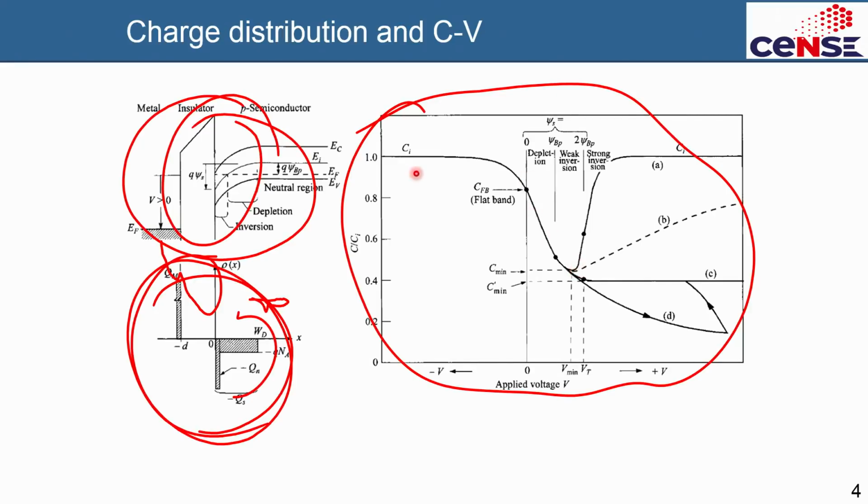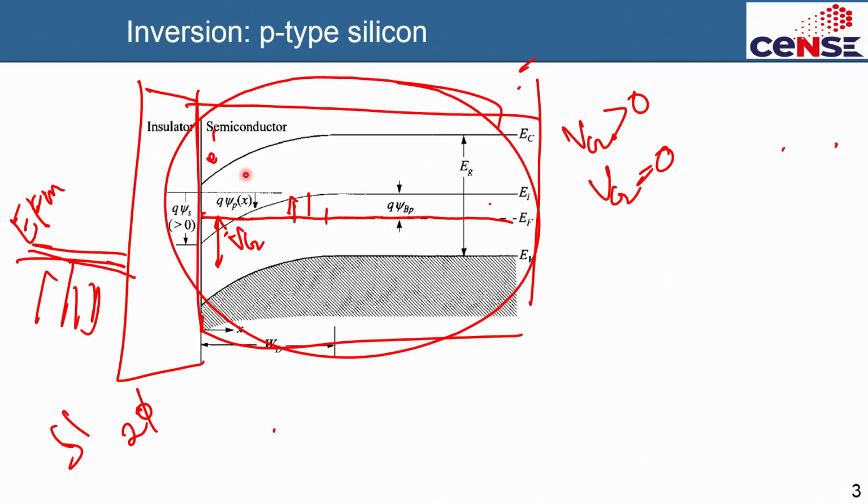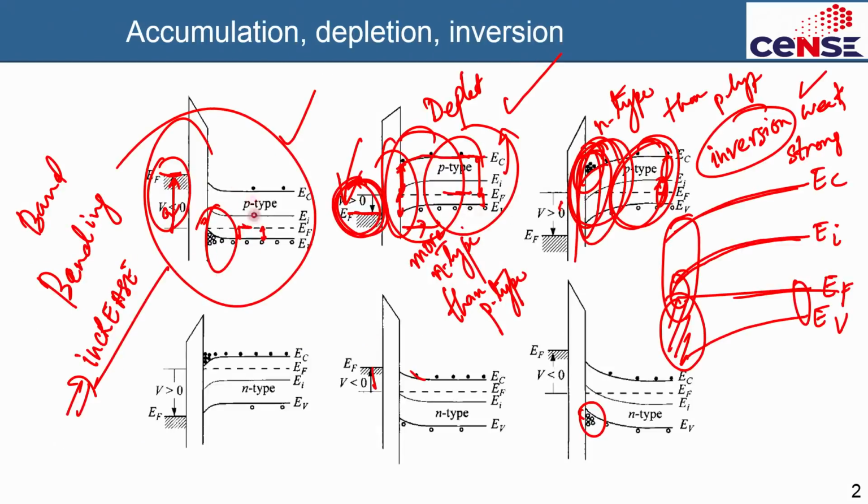It's a very, very important number. And if you recall this capacitance-voltage curve, I told you when you apply a negative gate bias, this is the negative side of the zero axis, you are going to attract more holes at the interface. So you end up with a situation where you have an excess of holes here, and those excess holes are majority carriers. They have no problem moving in and out fast.